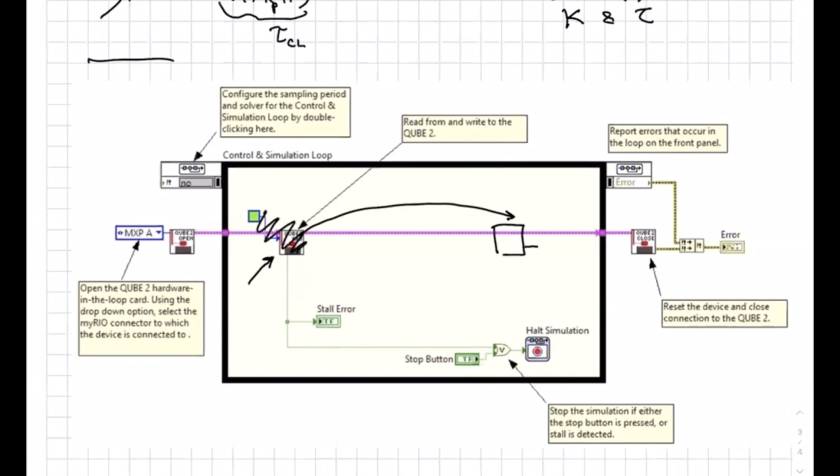So here's, and now take your little, this is your omega measurement, right? And come back over here, form a little, so here's gonna be the omega that you want. This is the omega that you measured. There's your error, right? Multiply it by a little gain, put a KP in there, and then this is your drive voltage right in there. So simple. And then this guy right here can go to a little plot. Show your output. Okay. So you're going to build that guy in the lab.